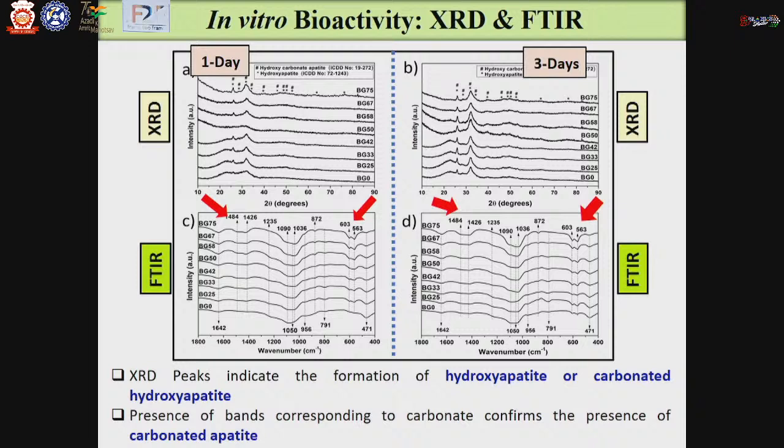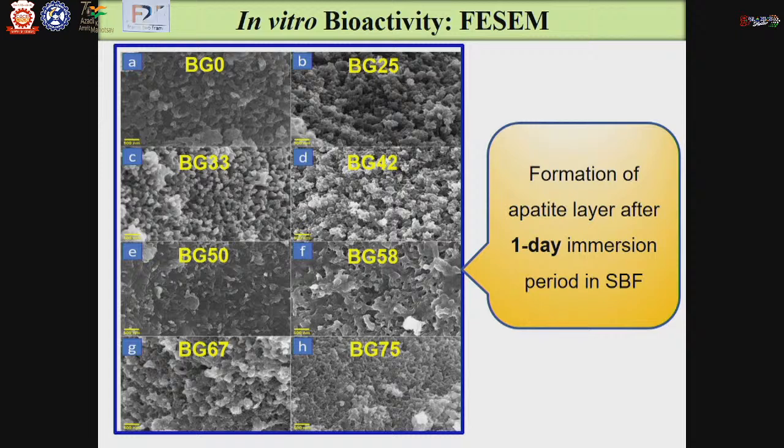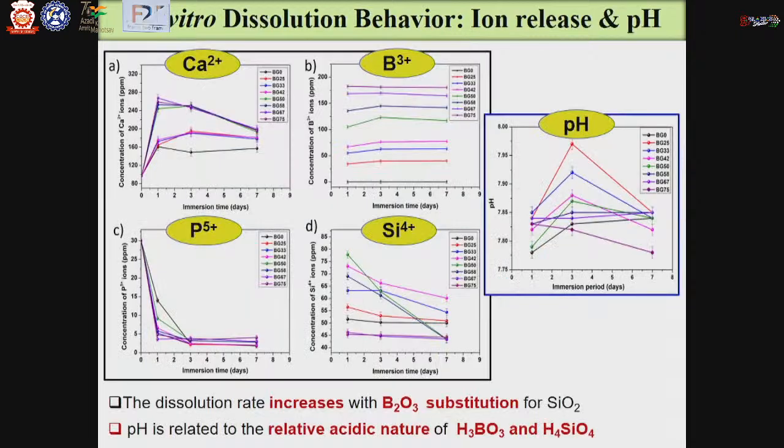We see upon 1-day immersion the formation of an apatite layer from XRD, but XRD cannot confirm whether it is a carbonated apatite or only apatite, so FTIR confirms it is a carbonated apatite. Now FESEM also confirms the formation of an apatite layer on the surface. This in vitro dissolution behavior was done on the collected fluid solutions after the typical immersion periods, and the dissolution